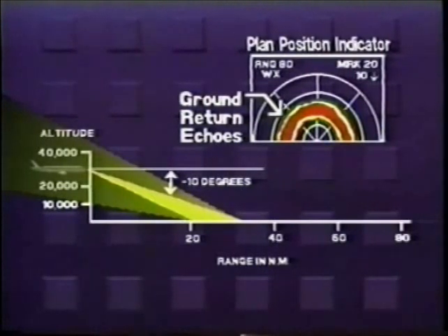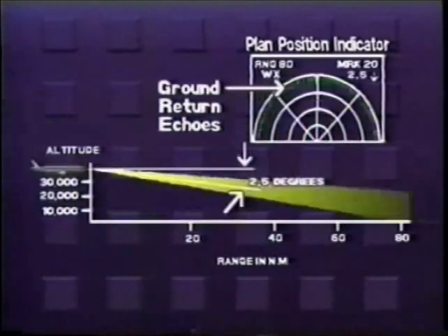At this point, you can think of the radar's beam as illuminating the Earth's surface in a manner similar to the way a searchlight mounted on the front of the airplane and pointed at a similar angle would illuminate the ground in front of it. Now slowly increase the tilt angle to lift the beam. As the beam is lifted, you'll be able to see the ground stripe reflection moving further out in range.